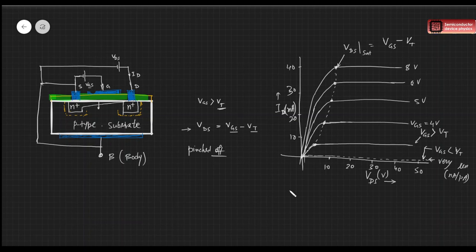Okay, so this is the IV characteristics for this. But again, one more thing is this current will not saturate exactly like we studied in the transistor, right? There is an early effect, and this current will not be exactly parallel to the x-axis. It rises slightly. There is a slight dependence on this VDS, or voltage between the drain and source. A slight dependency is there, but we take it as a saturation current. Okay.